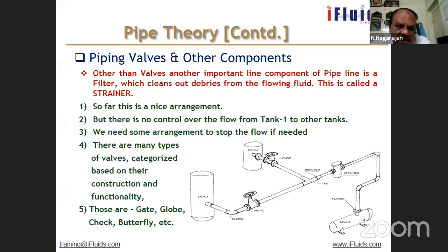The inside of the valve component is like a ball with a hole in the middle. It's a rotating sphere with a hole in the central part, and that hole will allow the flow through the valve. Okay. So you just remember different types of valves are available, and the type of valve will depend upon the process requirement.